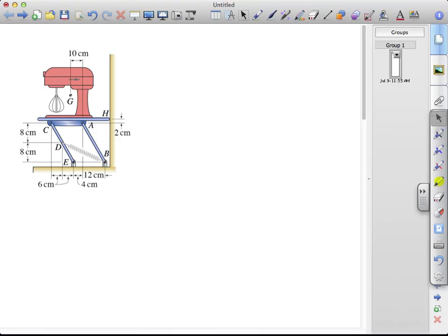In its absence, the rectangular configuration of members AB, CA, and CE is the kind of unstable assembly we mentioned in section 6.3. In the absence of a spring, the whole assembly will rotate counterclockwise and slam into the floor.